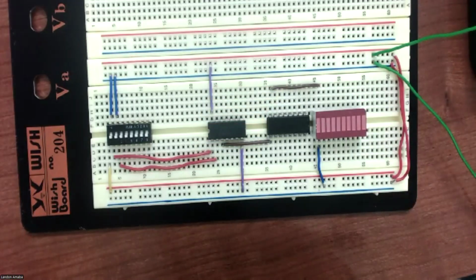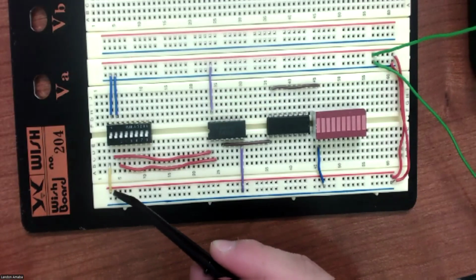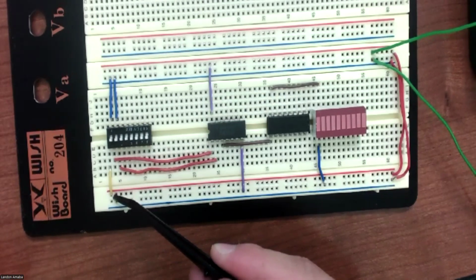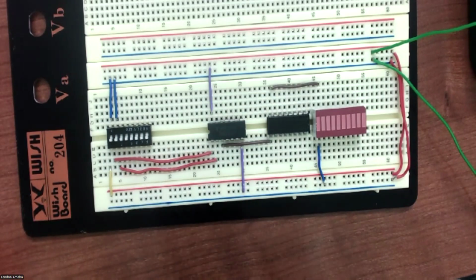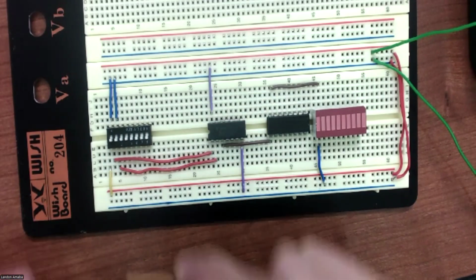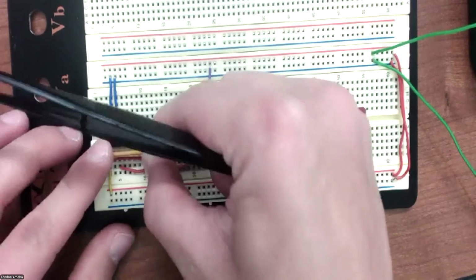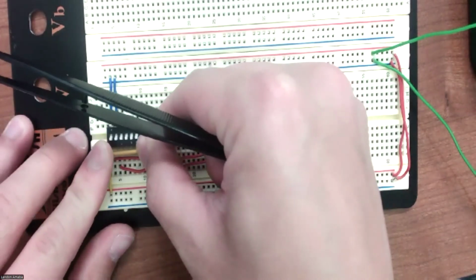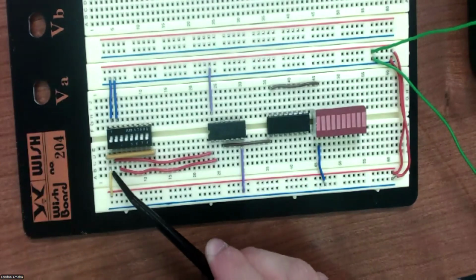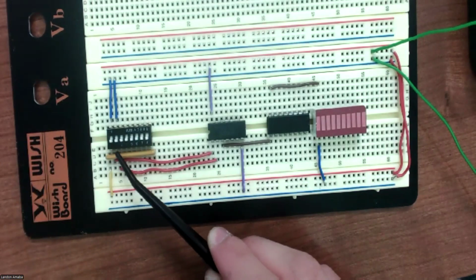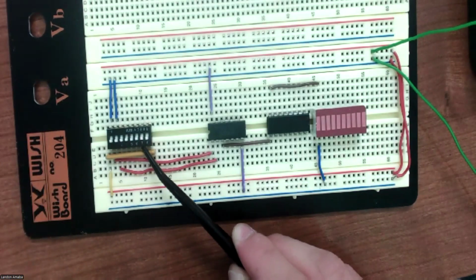This yellow wire right here is connected to our red power rail. So we bring this power onto the breadboard, and then we'll plug this SIP resistor back into the board. Now this yellow wire supplies power to our leftmost lead, the one that I double checked has a dot on it, which then provides power to all 8 of these switches.